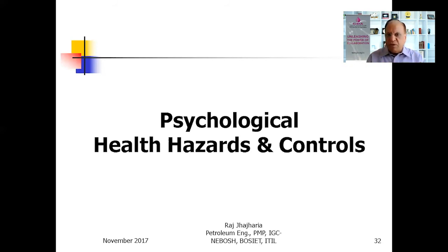It is not heavy on one side and light on the other side. It should flow easily from left to right or top to bottom. Make sure that this happens, otherwise this dry powder extinguisher is of no use. And second point, every extinguisher comes with a seal, and that seal should not be broken. If the seal is broken, that means this extinguisher is not reliable.